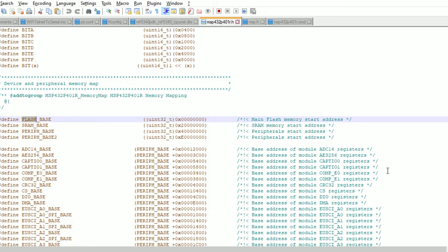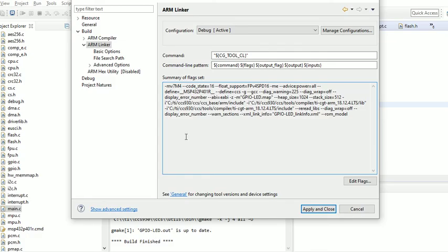We need to understand this so that we will know where the program needs to be stored and how the configuration happens. Hope we gave a little view of how things flow, starting from editing the program, then compiling the program, linking, what are the files involved in linking, and what is the configuration that we need to use for linking. Here we have used Code Composer Studio from Texas Instruments to explain for the MSP432P401R microcontroller.